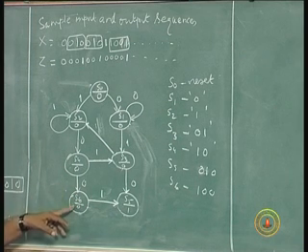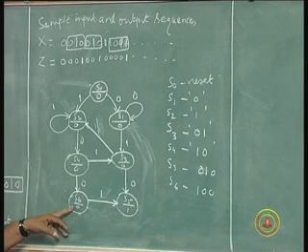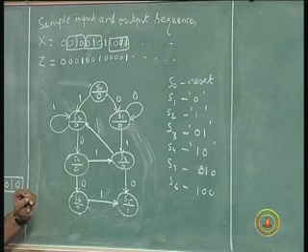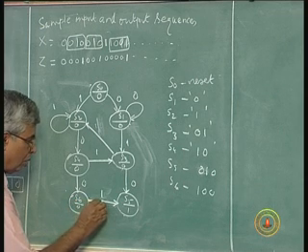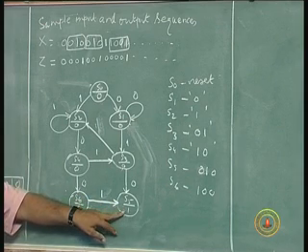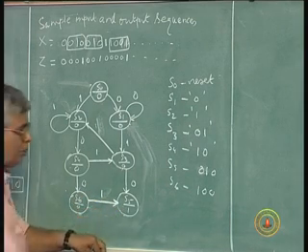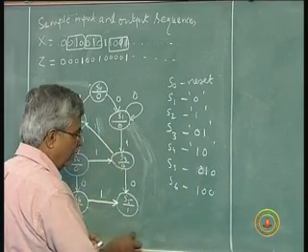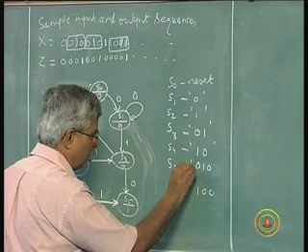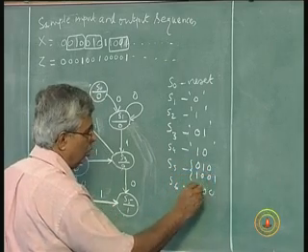Now, in S6 if a 0 occurs, there is no use, because 1 0 0 0 has no meaning except the last 0. If on the other hand, in S6 1 occurs, the pattern will be completed, the output will be 1. So, if in S6 1 occurs, we will go to S5, make an output of 1. Since there is already an output state with an output of 1, we will put this output here. That means S5 is a state where we remember 0 1 0 as well as 1 0 0 1, with both having an output of 1.